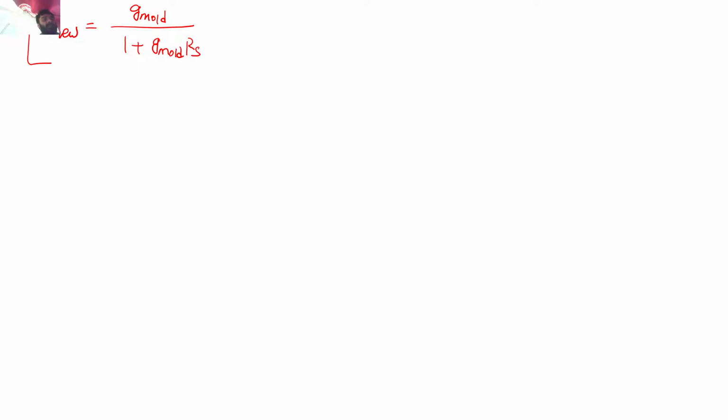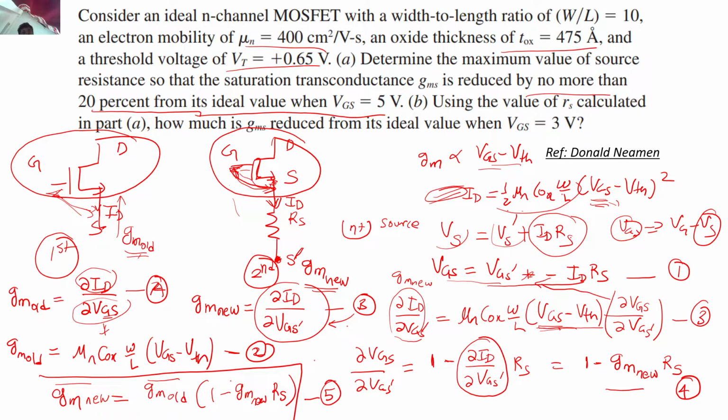Now you know I am a big fan of doing the sanity check, so let's apply one. You told me that Vgs will be lesser for the second MOSFET, and on the basis of that concept I told you that the new gm will be lesser than the older gm.